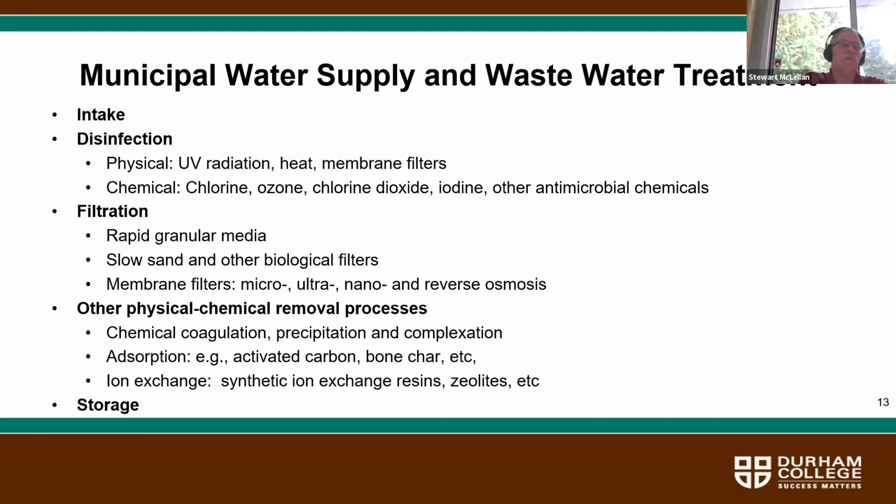If you look at Durham Region's intake for the Duffins Creek water supply plant, I believe it's almost a kilometer out in the lake, and you want those intakes to be somewhat away from the shore because the quality of the water is generally better when you're not pulling your water directly from the shoreline. So the intake is the first part.